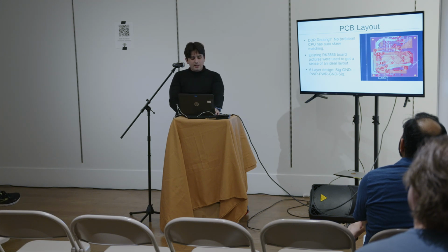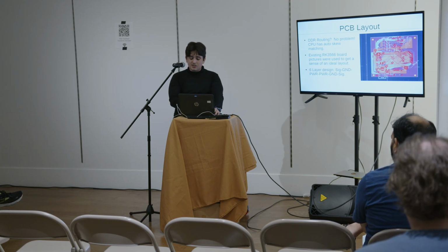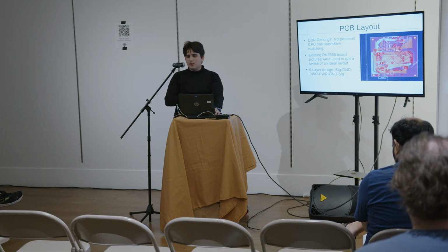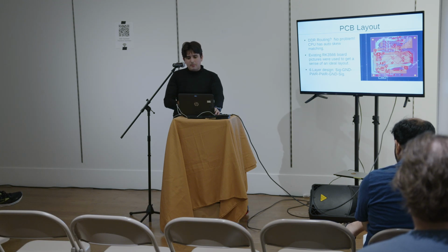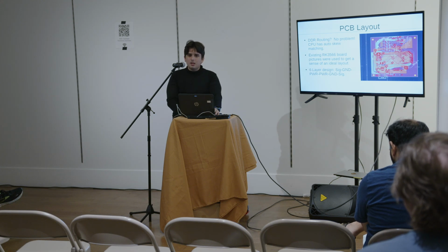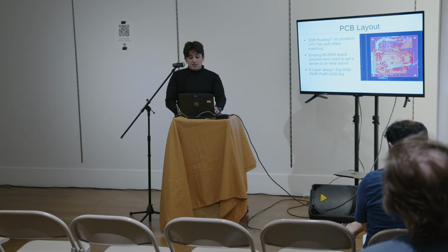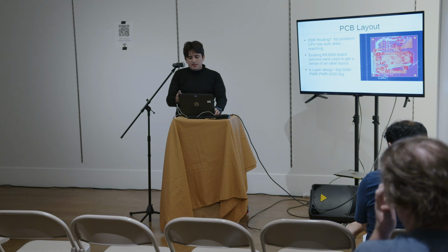Now, another of the key benefits of this stack-up is that since each signal transitions directly from top to bottom, there are no via stubs on the design. And you also do not need to back-drill the vias with your manufacturer. All these things will increase price and decrease signal quality. So by keeping all the signals between top and bottom, we really make it a lot cheaper and also a lot more stable to manufacture. Now, of course, it was very hard to achieve this, but it was very well worth the effort.